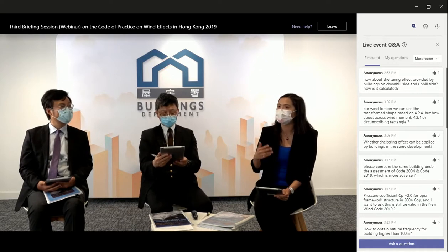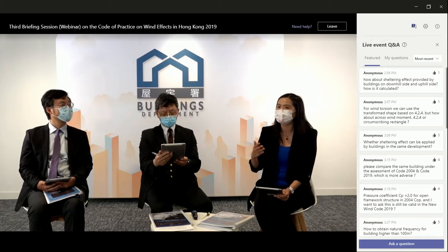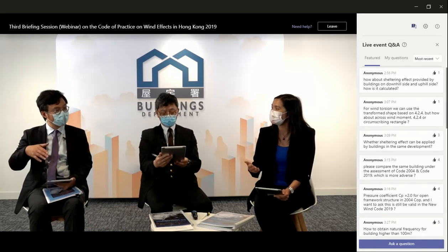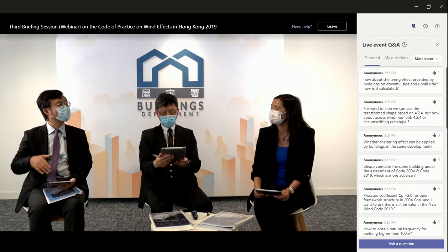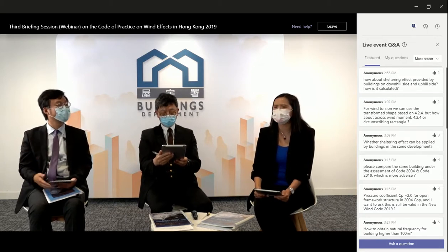The first draft of the frequency is assumed, and then they do the design. But in the future, maybe they need to readjust the frequency and the mass and recalculate, to know if it's still within the design range. Yeah, it's like an iteration. So they keep updating the finite element model and then they keep updating the wind load.